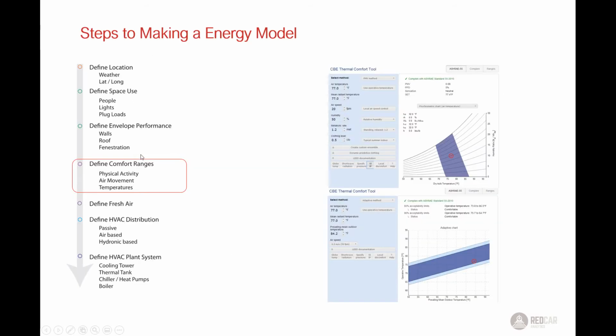So that's walls, right? So now we have our location, people in the building, how much thermal internal loads they're going to have. We've added some envelopes. Now we need to define thermostats and a range of comfort. So comfort is a huge topic in and of itself.